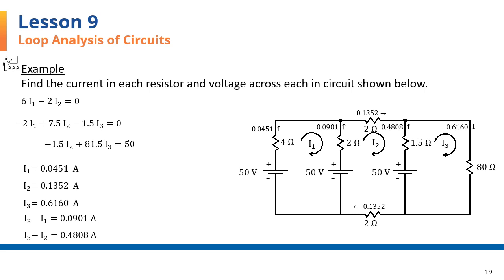I have marked each branch with the current in amps in that branch as well as the direction of each. Now that we have the branch currents, we do not need the loop current indicators or markers, and I'll remove those to reduce the clutter in the diagram. One check on our work is to verify the KCL for the nodes. Let's look at this node.